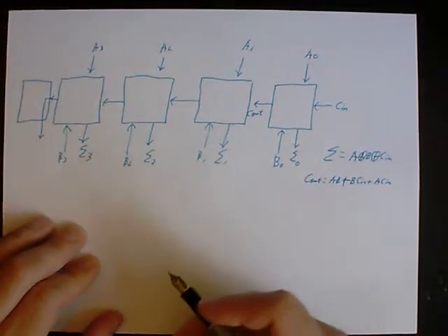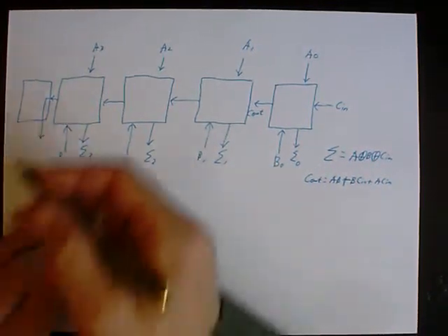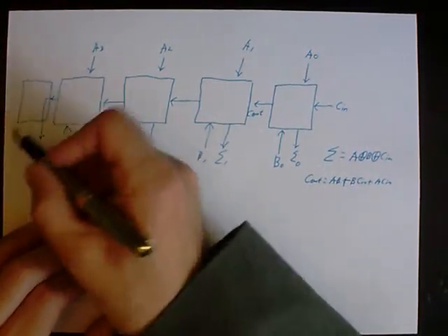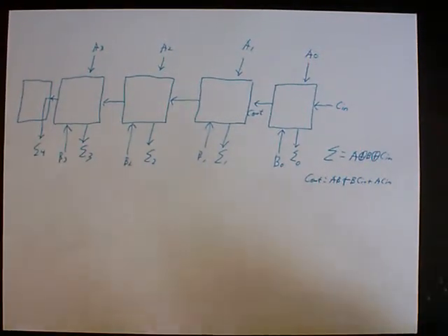And we can take the carry out from the final stage, and we can use one more cell on this row of cells to take that carry in and send it out to the south as a 4th sum bit. And there we have a 4-bit adder set up as an old-fashioned ripple carry adder implemented using 4 single cells.